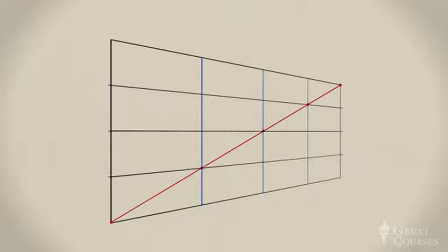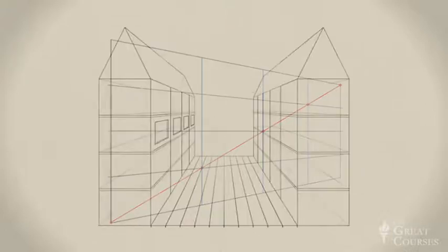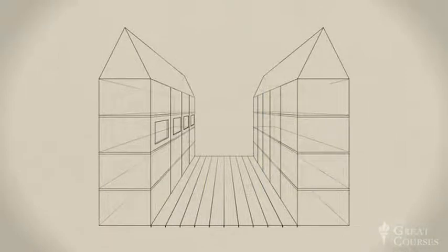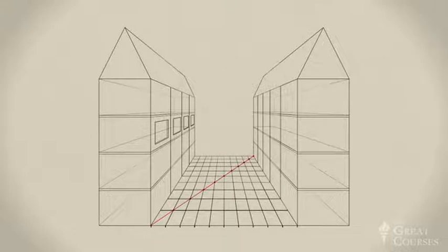We found the same thing holds true for a floor plane. In the quad's ground plane, we had 10 divisions along the horizontal axis, receding into space toward the vanishing point. We drew a diagonal construction line, corner to corner, traversing the plane. We noted the points of intersection and drew a horizontal at each traverse. Then erased the construction lines to reveal a proportionate diminishing grid.